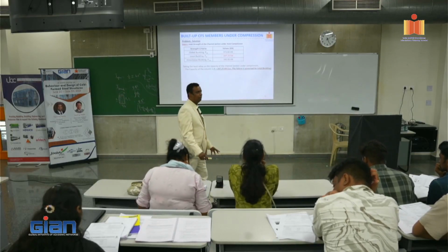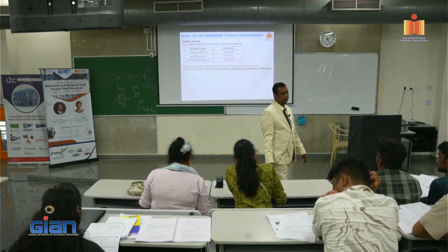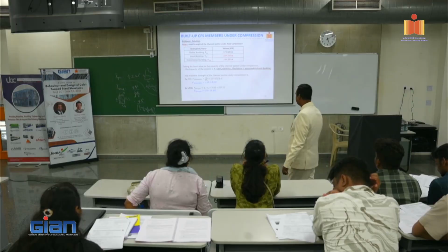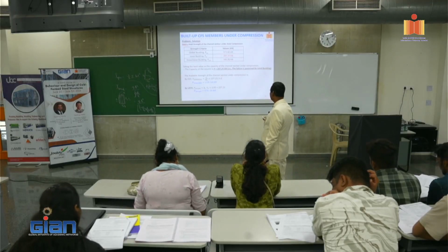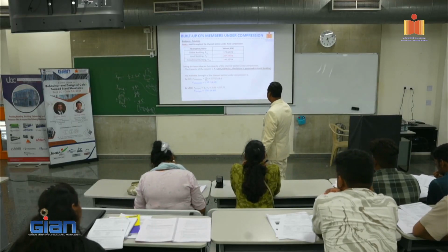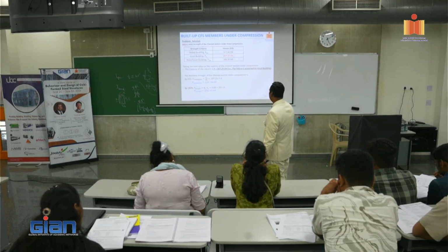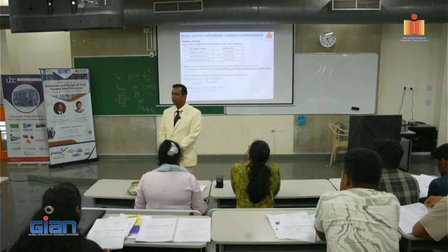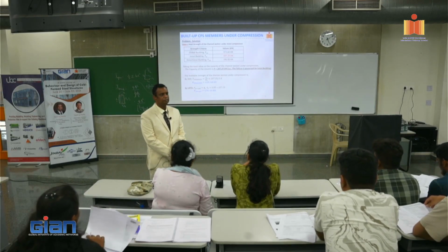Is that all? Then we have to put a safety factor, right? So we also have to put safety factors. So the safety factor according to this one is 1.8. You put it, you get 115. Or you can do it by LRFD, you can get 176.16. Right? So this is the safety factor that we have to use in our values.